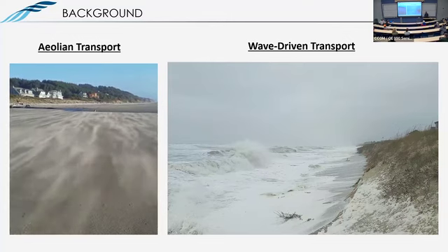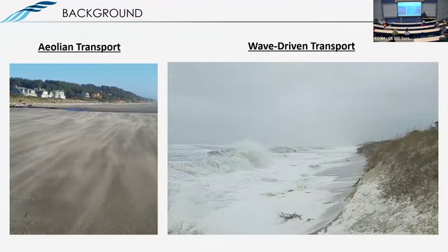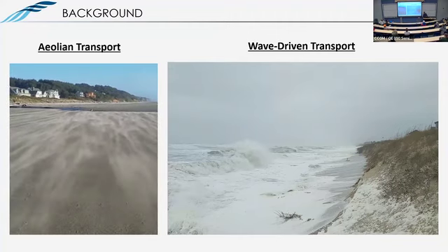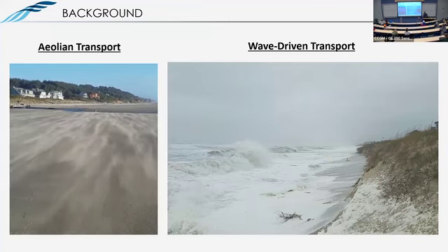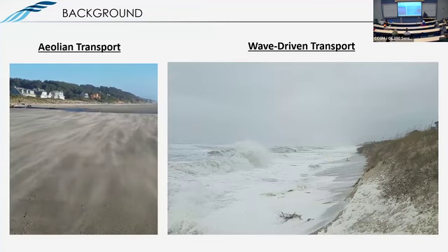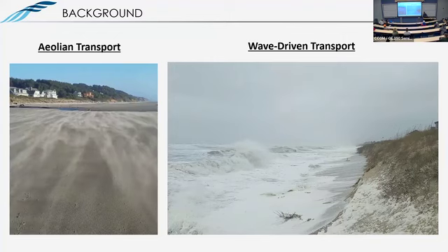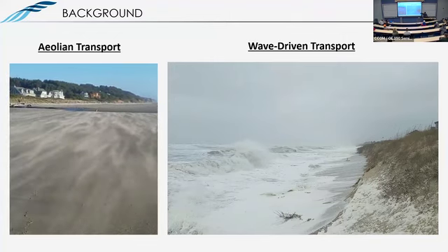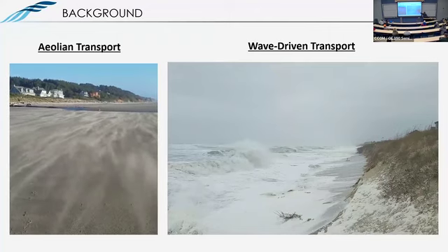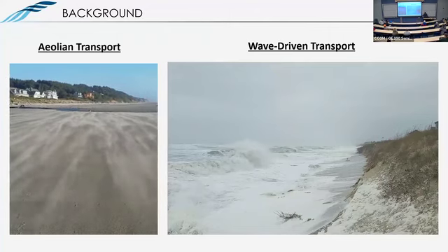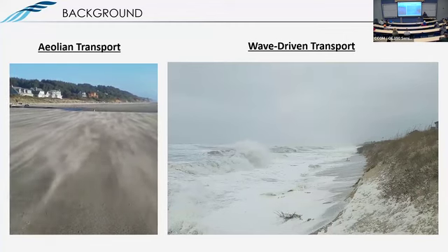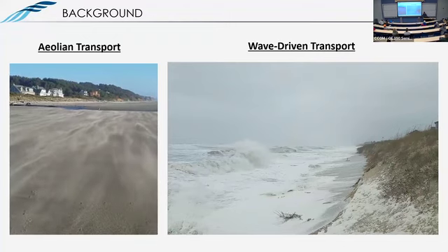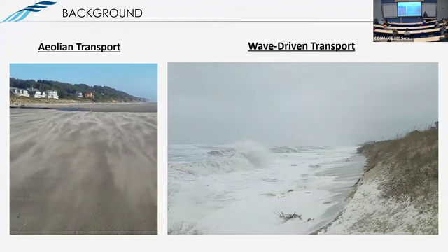Well, in all these measurements and videos that you see, there's a lot of intermittency in transport, and all of our simplified empirical equations basically assume steady state transport fields over long time periods, which we know isn't true. In reality, in coastal systems, let's say the threshold velocity for mobilizing that sediment is 8 meters per second. But if the wind falls below 8 meters per second, the sediment transport field doesn't actually stop. There's a second threshold for cessation that's different, and that's not something we include in any of these tools. So you have dual threshold effects.